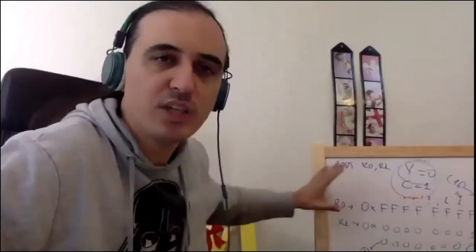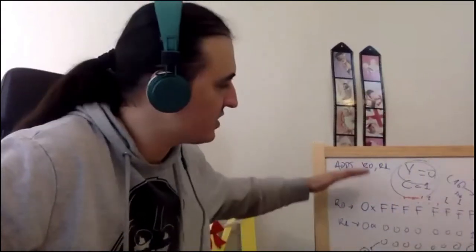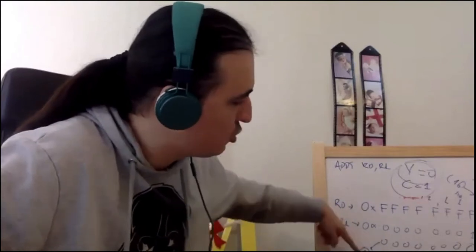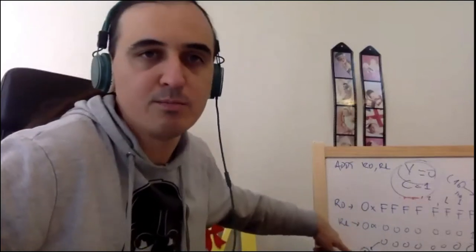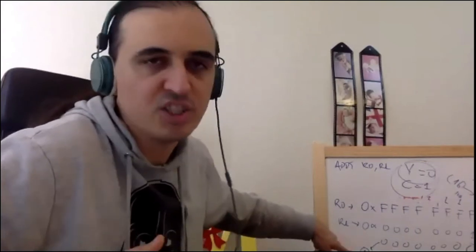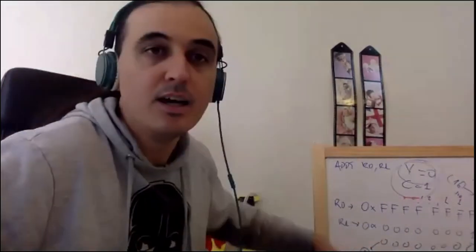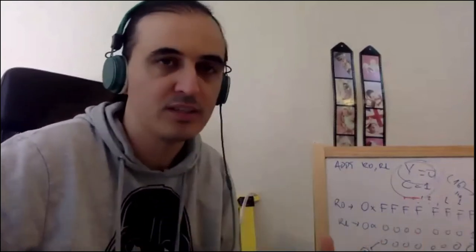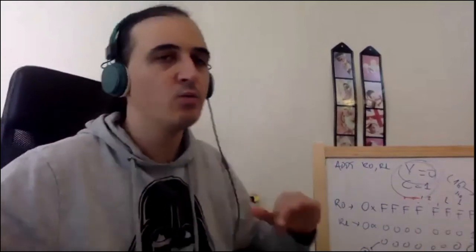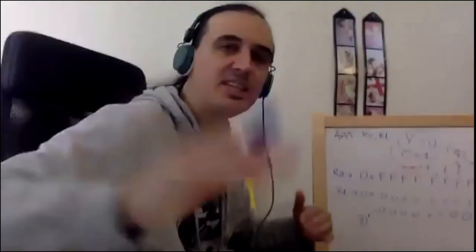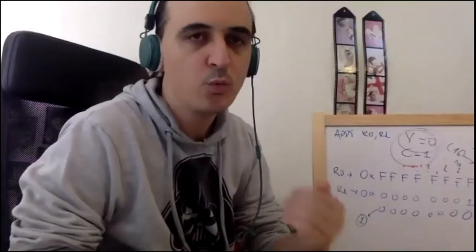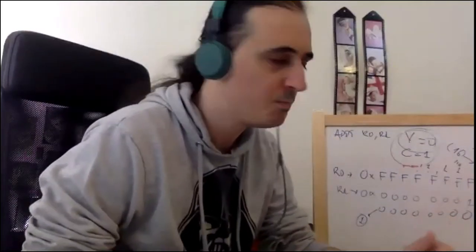Up to now, did you get what I did? I just summed these numbers up and tried to find out if there was a residual digit after the most significant bit or digit. So is this a V or is this C or both? I don't know yet. How do I decide? C is about unsigned numbers. V is about signed numbers, guys.